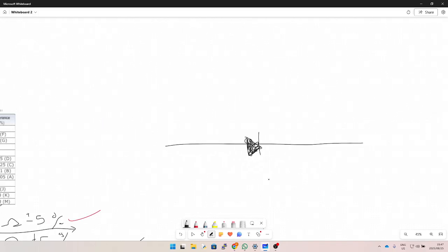Okay, right. The thing with the diode is this is the symbol. Obviously, you have to fill this in properly, but I'm not going to do that. It has two terminals. How do you know which is which? Using your normal current, which way does the electricity flow from? Positive to negative. So I have an arrow in front of me. Which is my positive terminal and which is my negative terminal? The one behind the arrow is positive, and the one in front is negative.